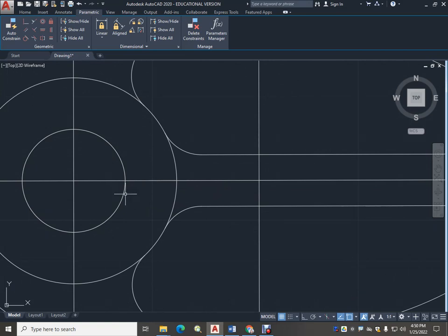Now the way this works is we're going to cut out a little section right here. And then we're going to insert a shaft. We'll have the opposite type cut into it so that we can drop a piece of metal in here. And then have our part. So the keyway is set at 3/8 by 3/16.